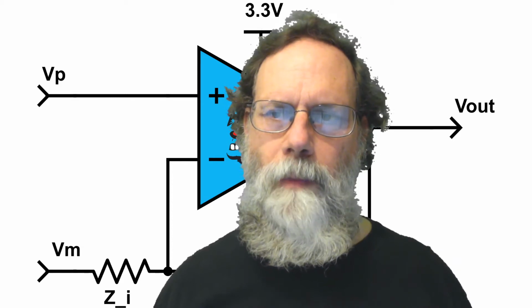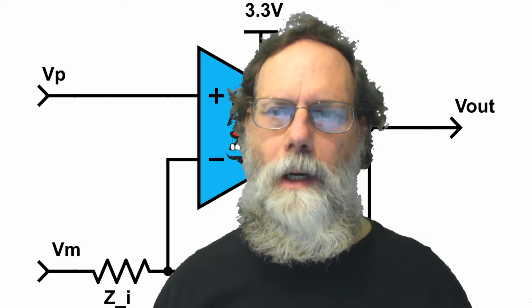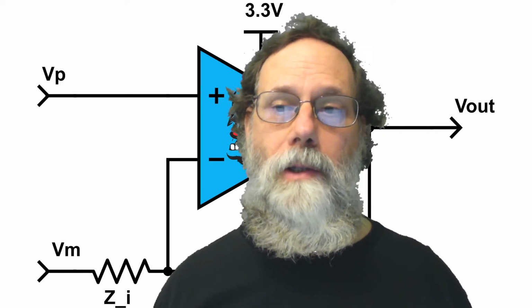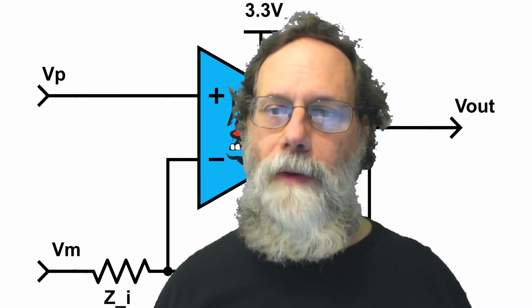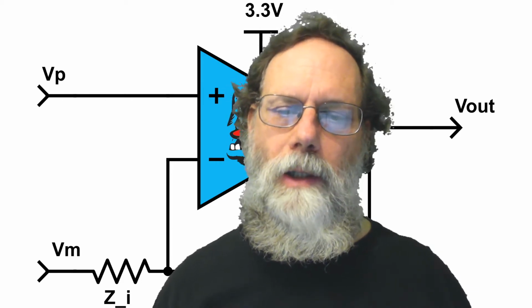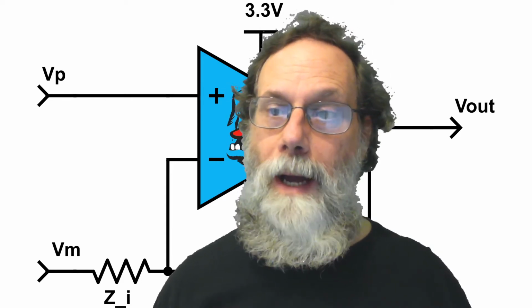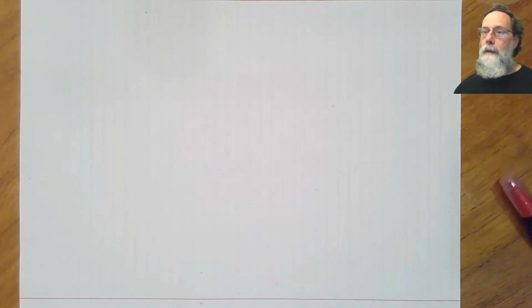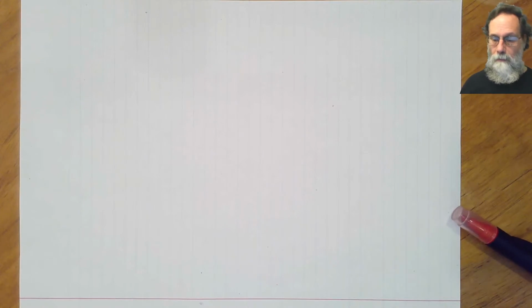This video is about getting more power out of a Class D amplifier, and it corresponds to section 35.5 of Applied Analog Electronics. Let's take a look at what controls the power of the loudspeaker. Basically, we can think of the loudspeaker in the audio range as mostly a resistive load. The inductive nature doesn't really come in until we get to higher frequencies.